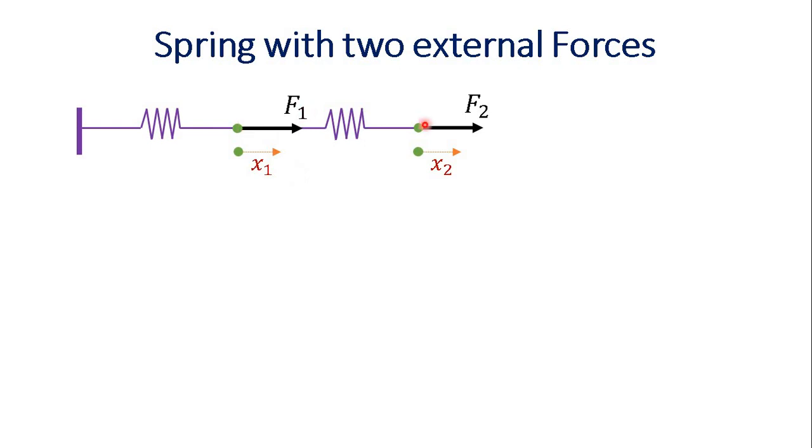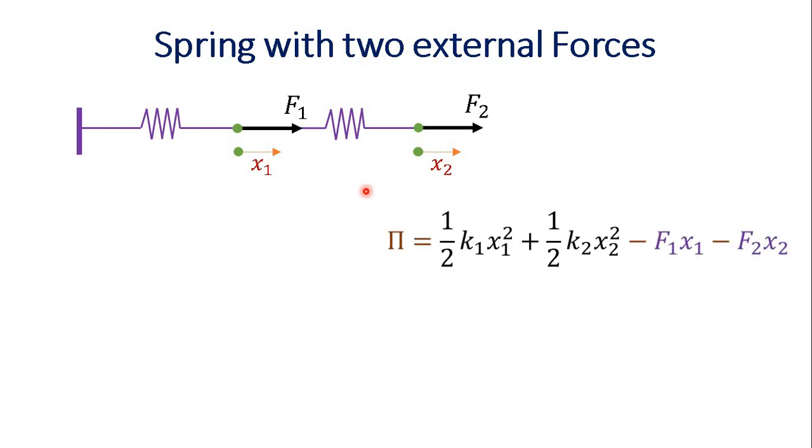So we have a two nodal problem, and we have to find the displacements x1 and x2 when the external forces F1 and F2 act at these nodes, node 1 and node 2. So after the application of forces, these nodes get displaced. The total potential energy that is stored in the system after displacement is written like this.